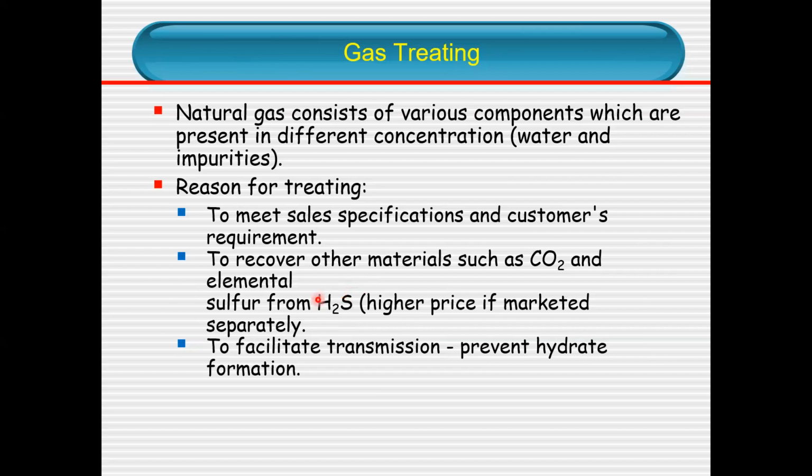At the same time, excessive water in the gas can also cause hydrate formation. Hydrate formation is basically like an ice cube. An ice cube that can block the crude oil or gas from coming out from the reservoir or formation. So even this you have to treat to prevent hydrate formation.